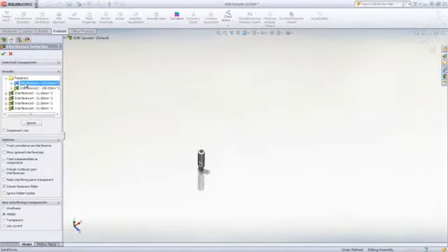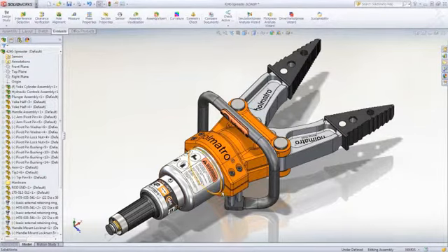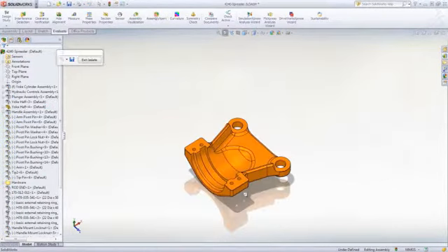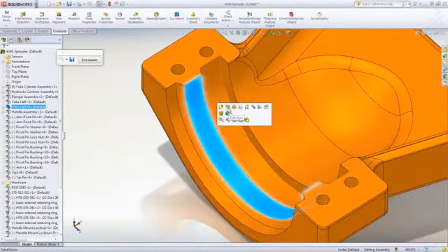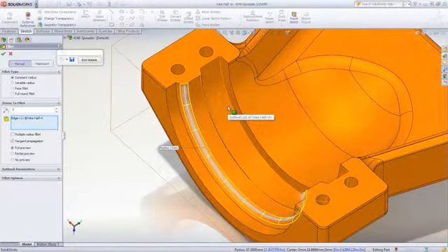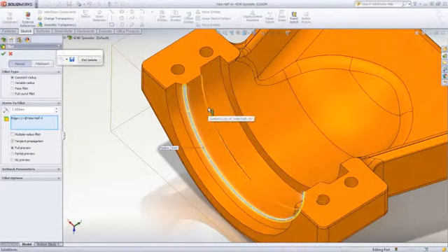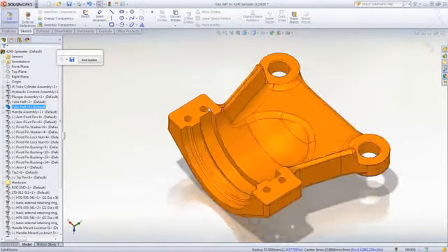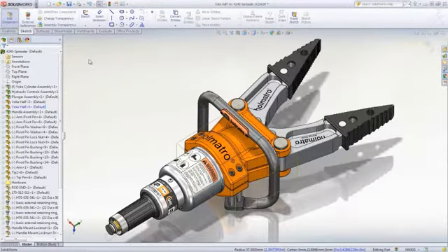A folder provides easy access to any fasteners that have interferences, and in this case, we can see that the fastener does not seem to be properly aligned in the hole. For each of these interferences, SolidWorks provides visual cues on the screen, as well as identifies the offending parts. Armed with this knowledge, we can easily rectify the situation. By adding a couple of fillets to the yoke, the clash is eliminated, since the same part is used on the top and the bottom.